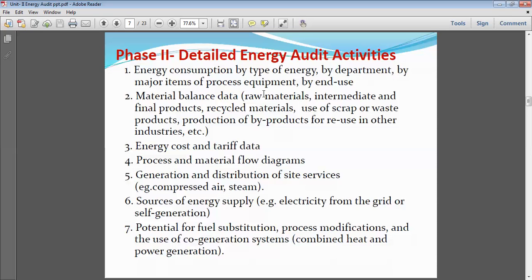Okay. So for 50 HP motors, we want to examine the power factor also. If the individual power factor of a motor is small, you have to improve it. You have to check the loading of the motor, which we are going to understand one by one. So I am just giving an example which is related to the type of equipment.